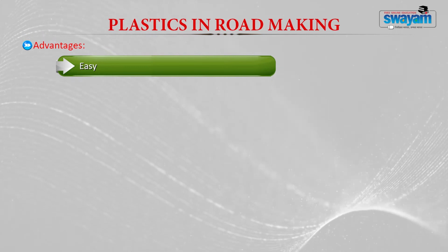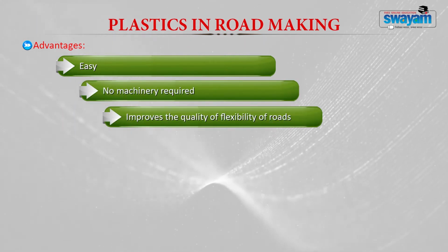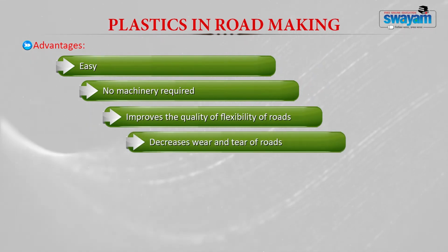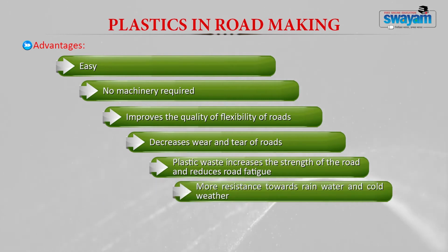Then, it is very easy, you do not need any machinery, and it improves the flexibility of roads. Further, it also decreases the wear and tear of roads. The plastic waste also increases the strength of the road and reduces road fatigue. The roads become more resistant towards rain, water and cold weather conditions.